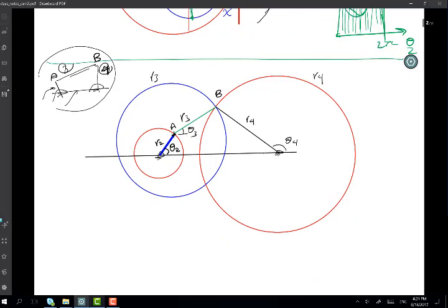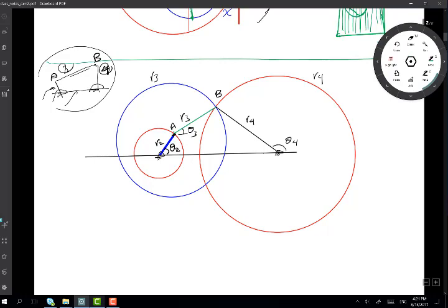Again, just to alert you to something designers need to be aware of, the fact that my two circles, the R3 and R4 circles, intersected at 2 points just suggests to me there is another solution, right? So there is another linkage. In fact, I can draw another assembly for the same R2, like for the same position and location of the crank. I have two possibilities for my linkage, and they are really two assemblies.